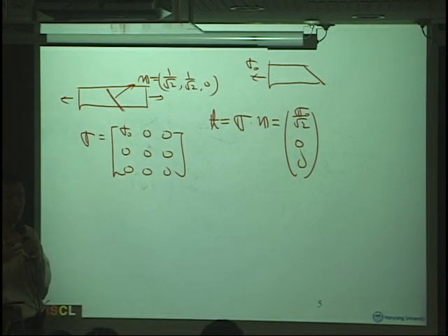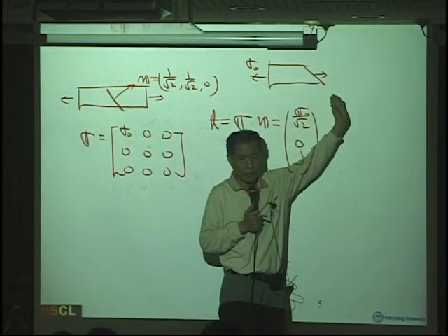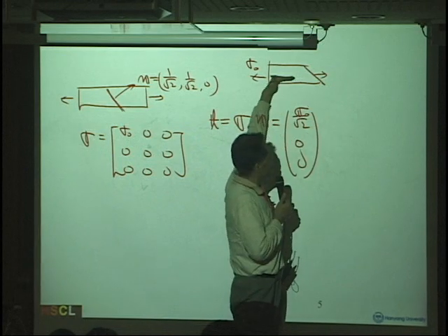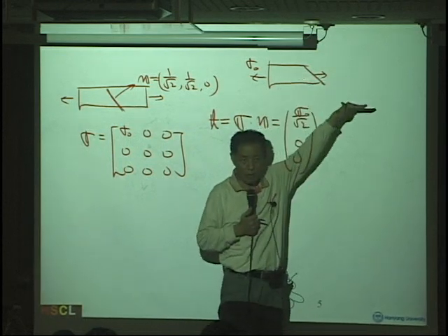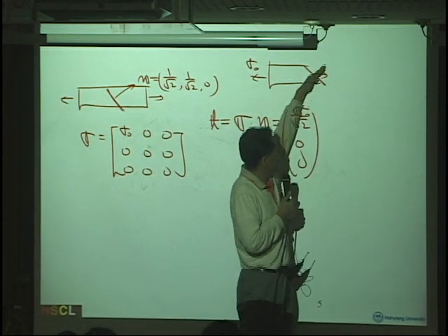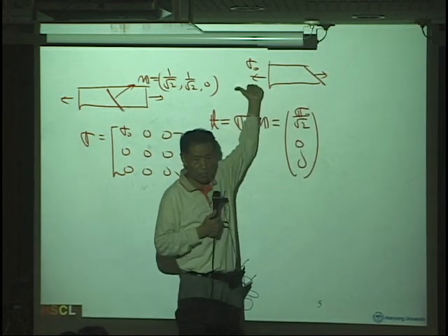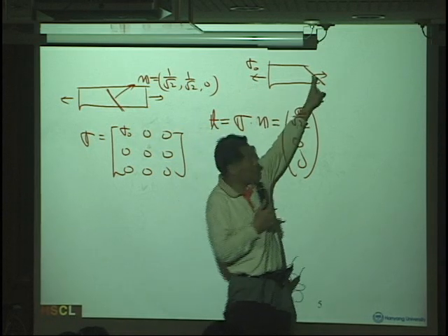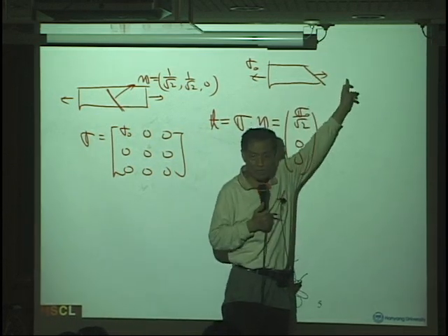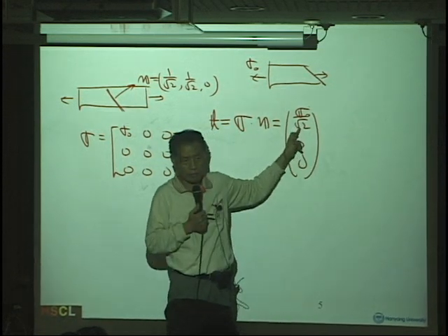This is very important, and we already covered it, but I am explaining it in another way, using some mathematical equations. Even though we have a cutting plane, the resultant should be in this way. The resultant force on this surface cannot have a certain angle because of equilibrium. We only have an x directional force here, and so at this plane we only have this x directional force. Am I right? Yes.